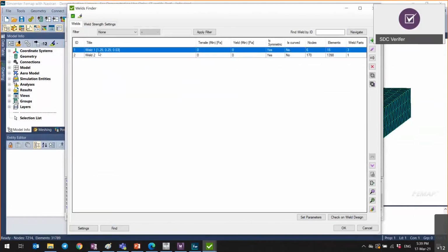So we have weld 1, which is a plate element weld, and weld 2, which is a solid model. As you know, we use stresses for fatigue calculation. So this approach is only for summarizing the force. So we use forces, summed forces over the weld length for the weld strength calculation. So the solid welds are possible to define now by adding it by hand, and they are available for the calculation of weld strength checks.